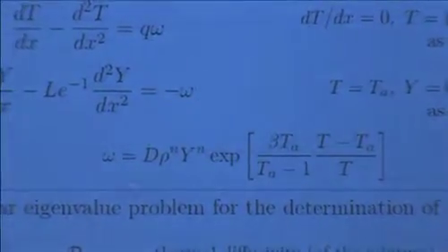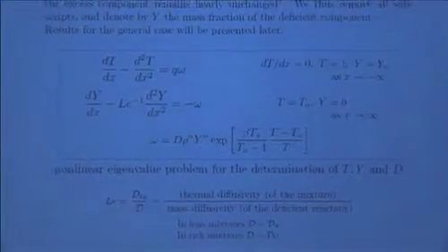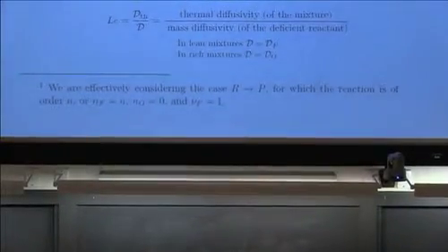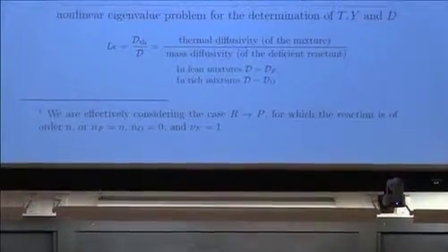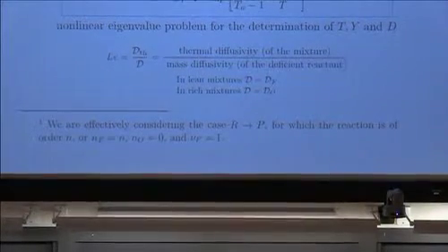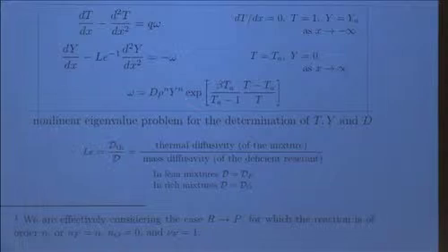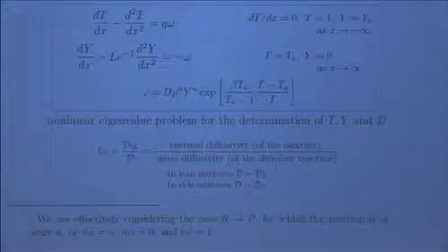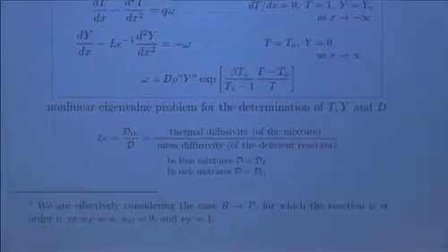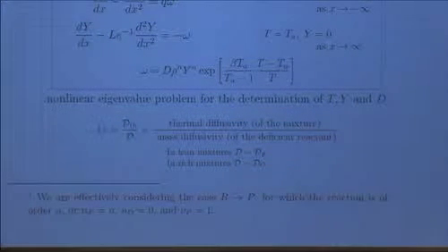And therefore, equivalently, it's like talking about a case where reactant goes to product, and the other reactant, namely either the fuel in a rich system or the oxidizer in a lean system, is in large quantity and doesn't change much during the reaction. And equivalently, it's also taking NF to be N and NO to be 0. So you can think of this as being a 0 order in the reaction, a 0 order with respect to the oxidizer, if you like. Well, they are all equivalent.